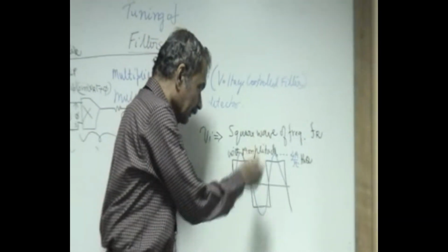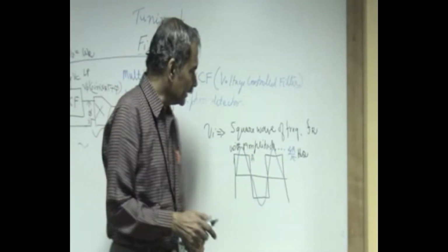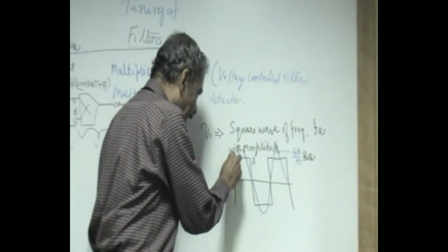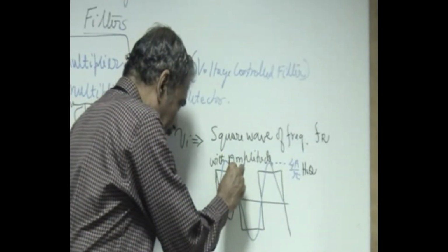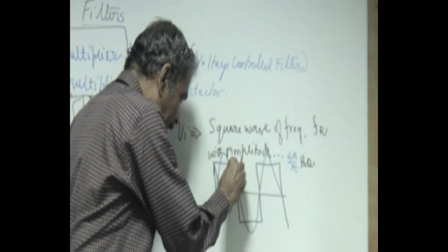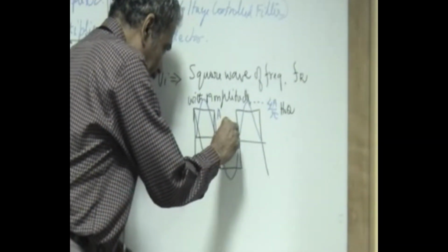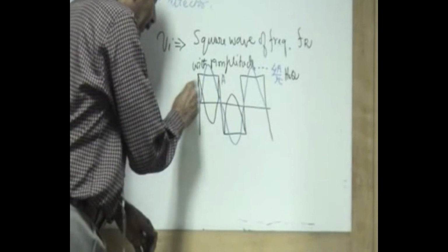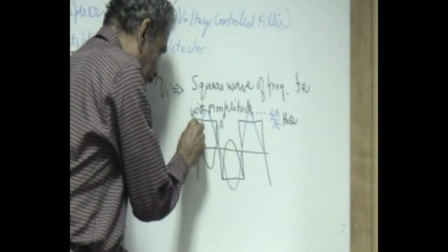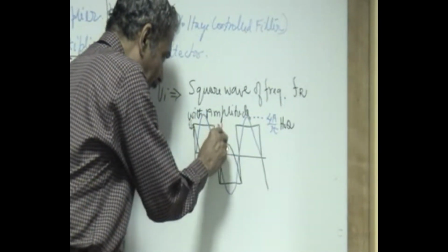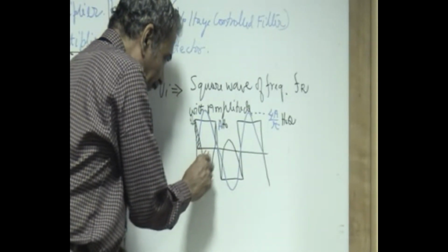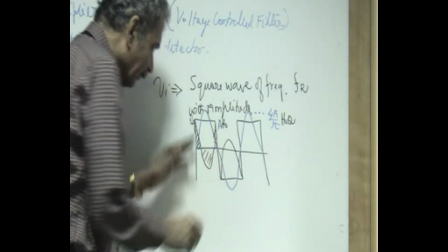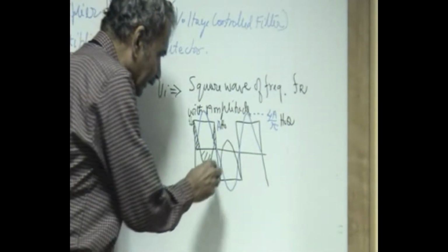And at the notch filter, we get this exactly subtracted from the input, and so it is going to be H naught into A at the output with a waveform which can be easily analyzed. It's nothing but the square wave minus the sine wave, fundamental.